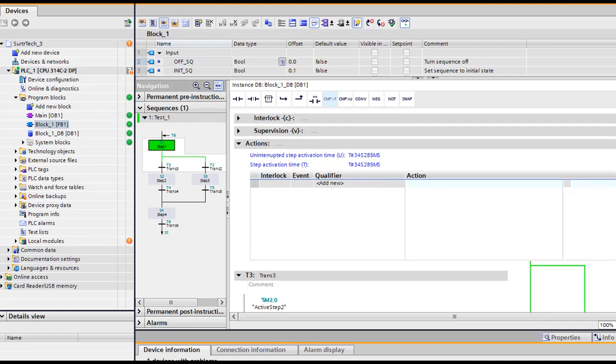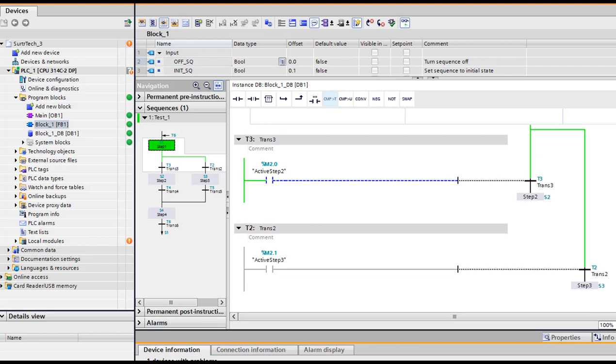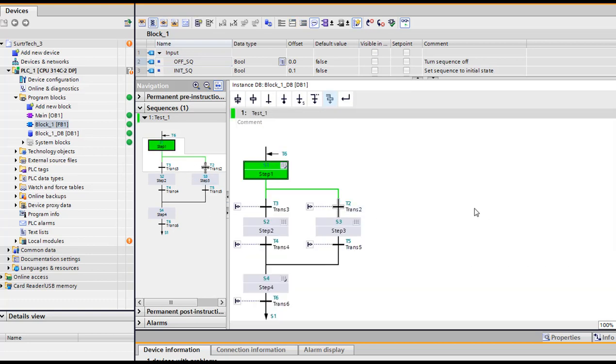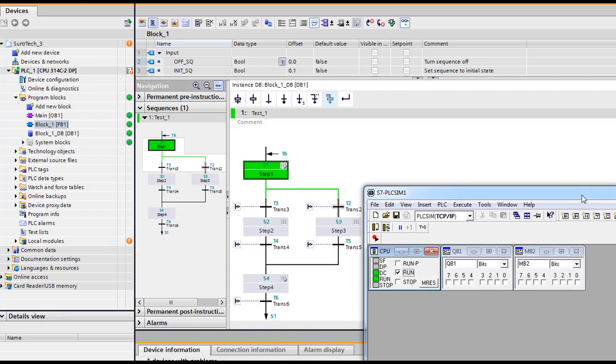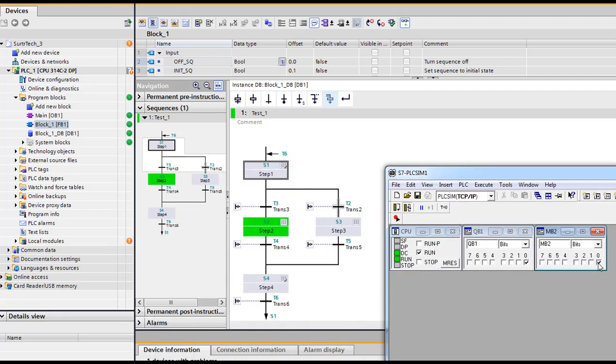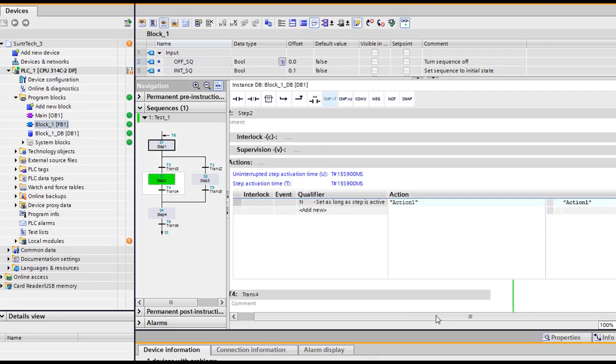We just have no action. Here the program is waiting in one of the steps, either M2.0 or M2.1. As we can see, the green line arrived there, but they are stopped because none of them is activated. So as we said, we're gonna use this 2.0, and here we pass to the first step. In the first step I have this output activated, which is 1.0. Double click here and 1.0 is active.